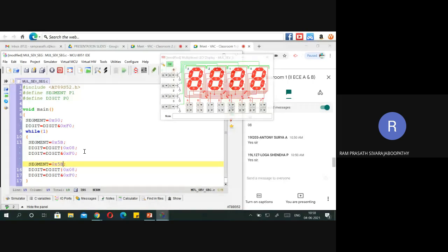Kindly help me out. Or else you can do one more thing. Already we have the 7 segment code for common anode configuration. You just complement and write the data. Both are going to be the same only. Fine. Okay, what about the 7 segment for 0?